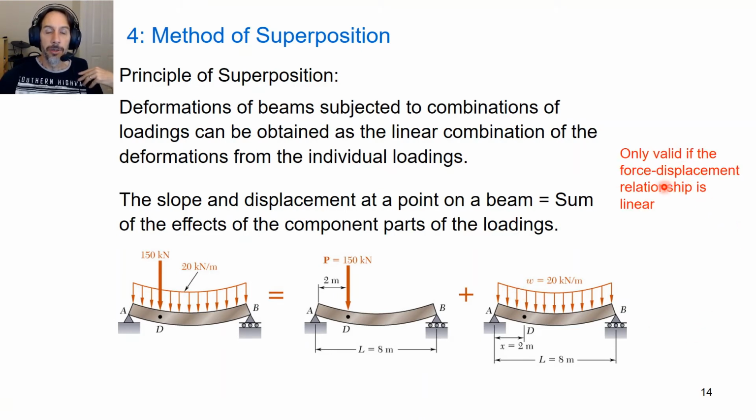An important thing to note though is that this simple addition of the two deflections or slopes from the two loadings is only valid if the force displacement relationship is linear. If you have a non-linear force displacement relationship, a non-linear material, or more likely large deflections, so it's a geometric non-linearity, then you can't do this simple addition.